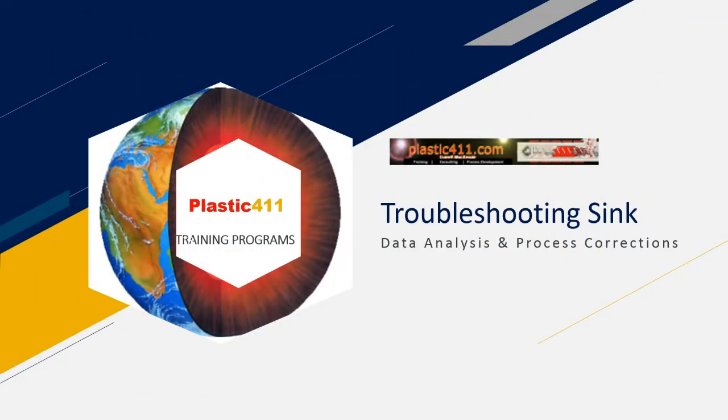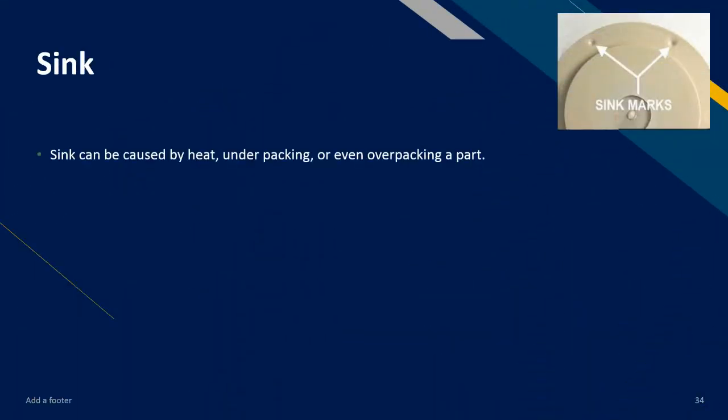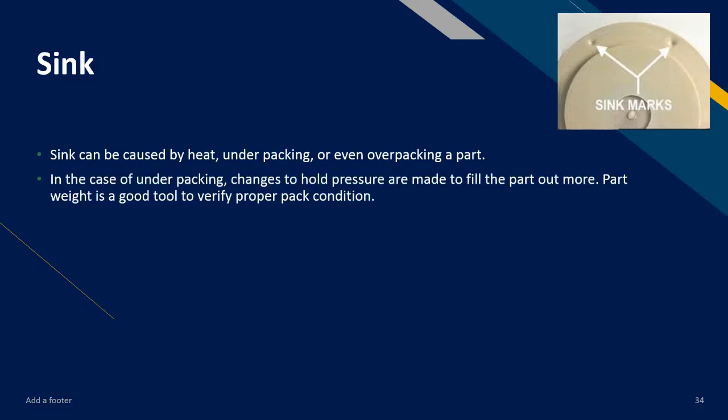Now let's take a look at troubleshooting sink. Sink can be caused by heat, underpacking, or even overpacking a part. In the case of underpacking, changes to hold pressure are made to fill the part out more. Part weight is a good tool to verify proper pack condition.